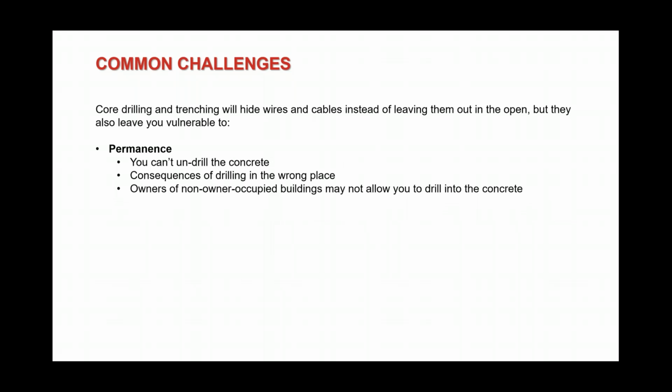Another issue we have with this traditionally is once that concrete is drilled, you don't undrill it. Oh, you can fill it in with concrete, you can fill it in with fire stop, but you just don't undrill that. And we have seen it so often where the core drill has been in the wrong place.